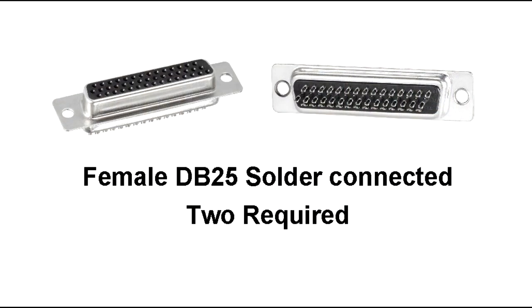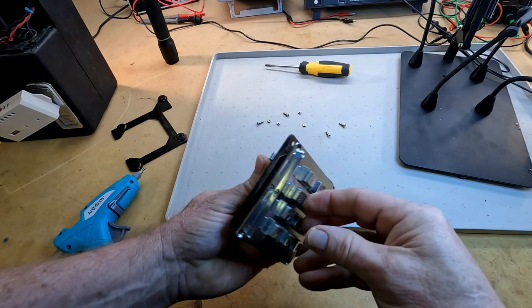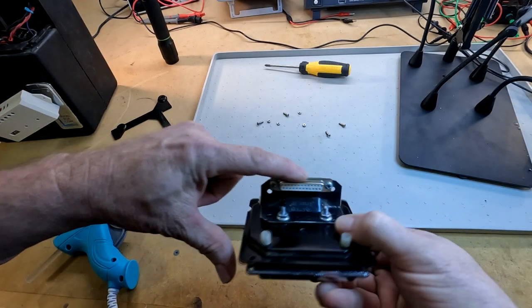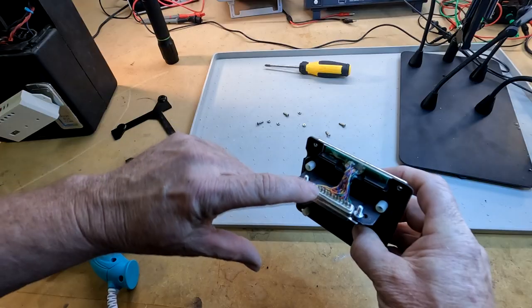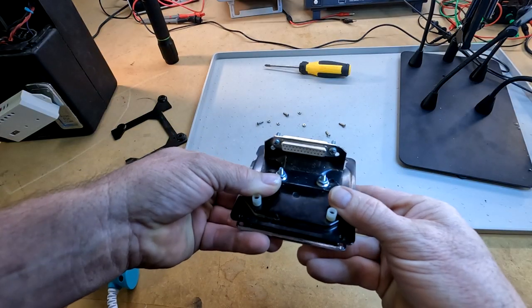You will install and physically secure a female connector at both the detachable front and the inside of the phone. The cable will have two matching male connectors. You will solder your new keypad wiring to the female side and then securely install it using your own customized mounting. The same procedure will be done on the interior of the phone.